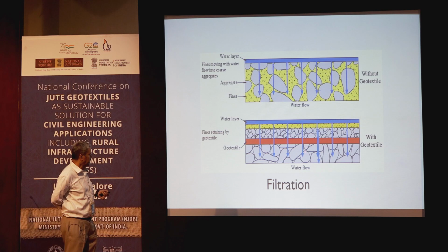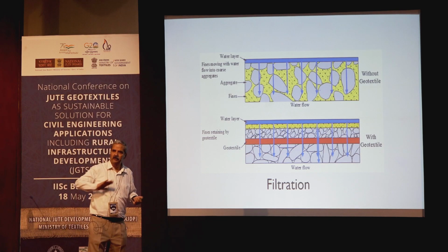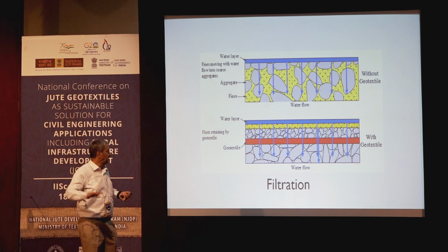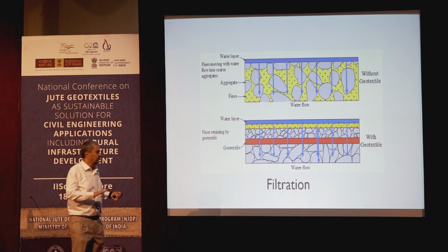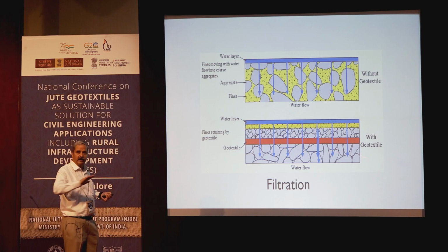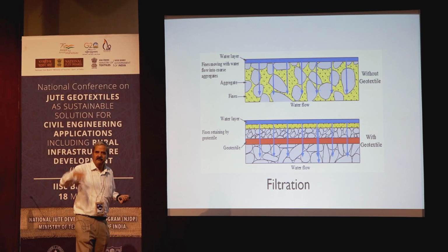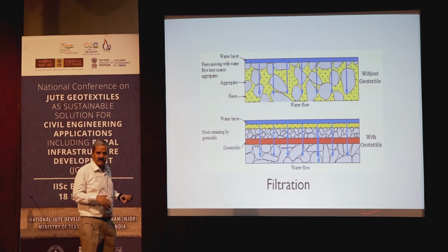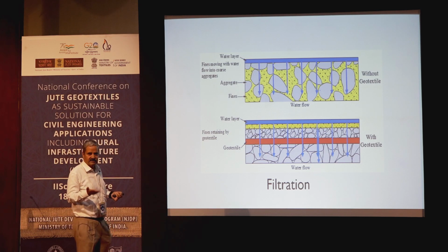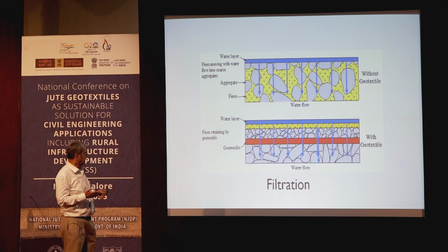You have an aggregate here, a subbase here, and other layers like the wearing course and bitumen layer. They're expected to perform in their own way, because when you design, they behave independently and very well. But under the influence of water and traffic loading, everything gets mixed up. If you have a geotextile layer as a separator and a filtration layer, then it helps a lot.